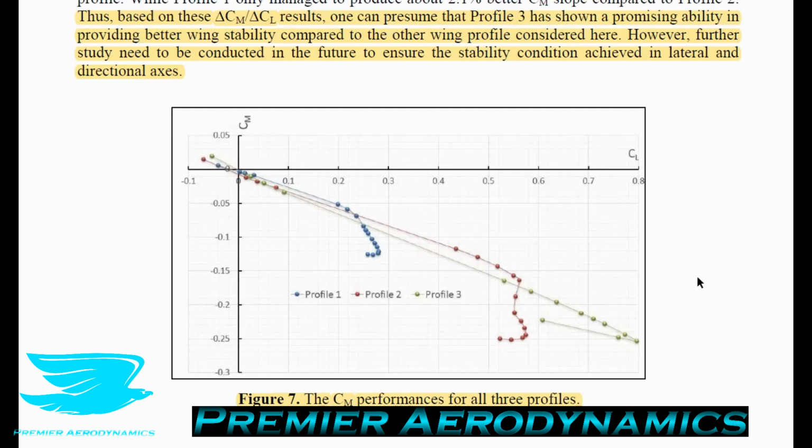So that's very good. Now I looked up the moment coefficient for a NACA 0006, which I mentioned earlier, is a comparable airfoil to these airfoils to some extent. And the moment coefficient for those airfoils is terrible, like they're all over the place, whereas these ones are very good. So this shows that in terms of this airfoil, the NACA 0006, these Zimmerman airfoils are much better. And the reason why I picked the NACA 0006 as well is because they also produce similar lift coefficients at angles of attack comparable to these.